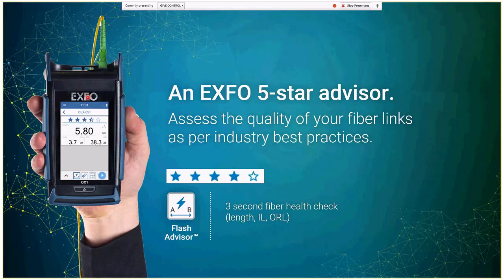Again, I have 5.8 kilometers of fiber. I have a loss of 3.7 dBs. I have 38.3 ORL. Is this good or bad? So imagine that you are working with a team of 5 technicians or 5 field engineers that go out and bring you these values. How do you know if they understand whether the values are good or bad?